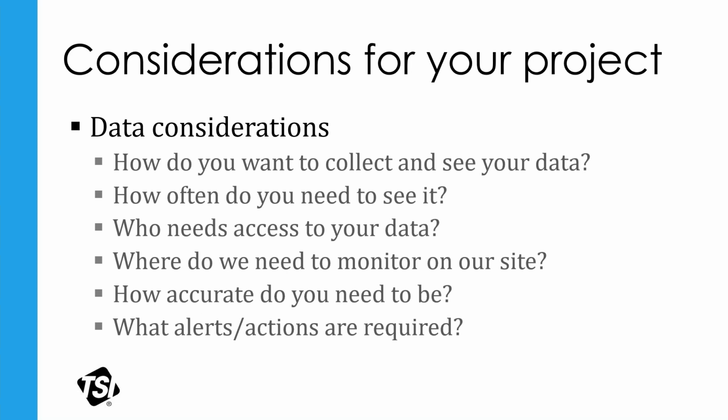Obviously, where to monitor on our site always comes up. Like, where do I need to put monitors? If I just put one monitor, is that enough? I don't know. Maybe. Typically you're going to see an upwind and/or downwind monitor on site, so you can have that differential to see, hey, is our activity actually adding to the dust that may already exist in the environment? Maybe it's based on, you might have multiple activities on a site, and you need monitoring points at each one of those activities because you need to see what's going on at multiple places. So certainly something to think about.